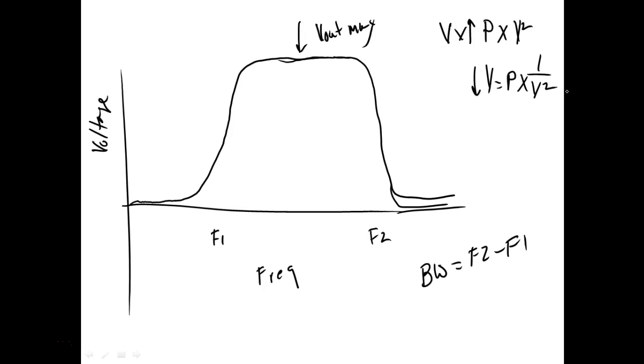You don't understand that? Well, when would the half power point occur? F1 would be when my power drops down to 1/2. But the problem is we don't measure power. We've got to figure out when I hit that 1/2 power point relative to voltage. So what would my voltage drop down to get that 1/2 power point? It's a number we use all the time.